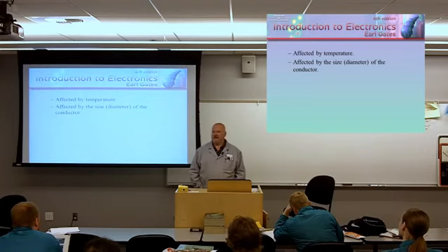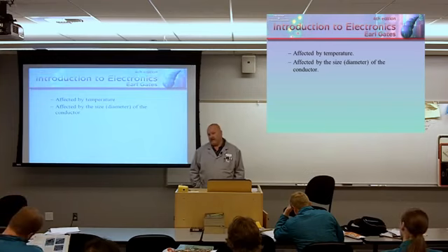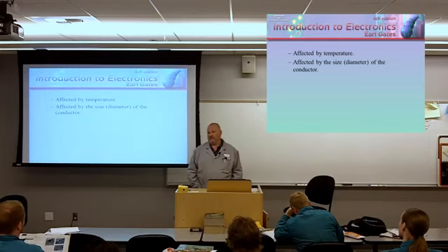The more energy you transfer from the source to the load, from your amplifier to the speaker, and that's a good thing. So generally speaking, you want to use the thickest conductor that you can afford, or of course adhere to standard manufacturing processes. And there are tables that you can find that show specifically what is required.